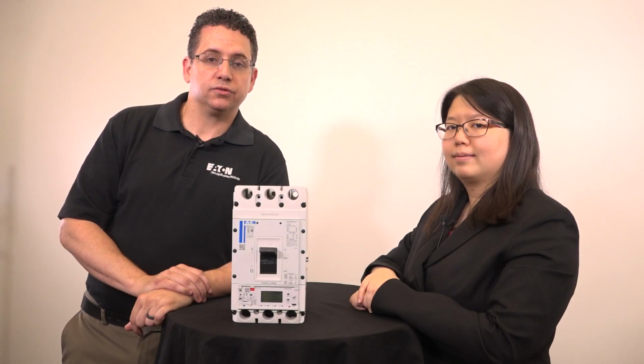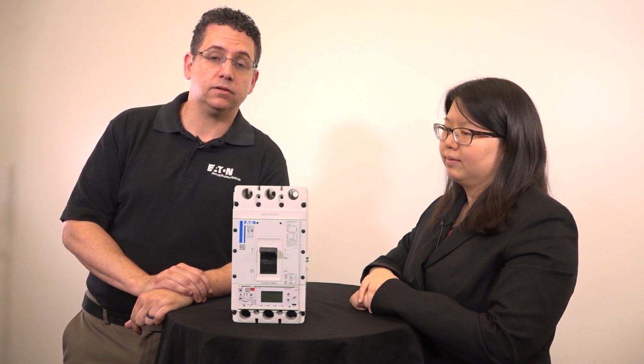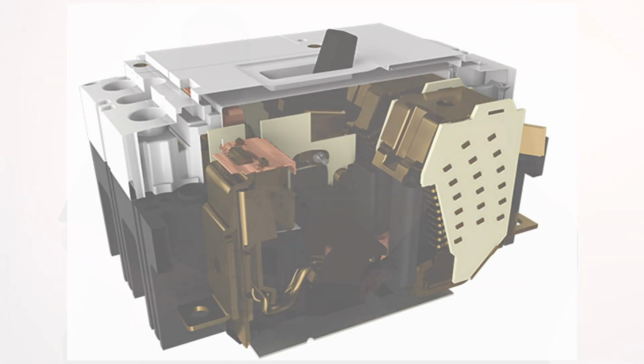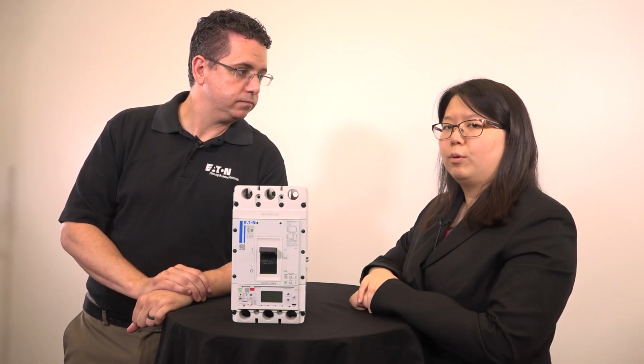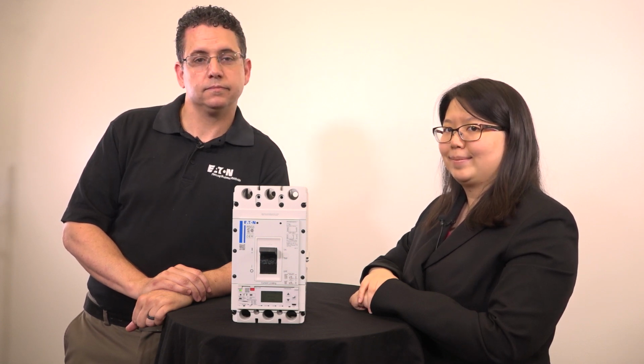In the early 20th century, trip units were purely mechanical devices. They didn't have electronics in them. The first trip units were just a piece of metal, called a bimetal, which would bend over when the current passing through it would heat the metal. Eventually, the trip unit would push the trip bar and open the breaker. Eaton still offers thermomagnetic circuit breakers, available in the Power Defense line.